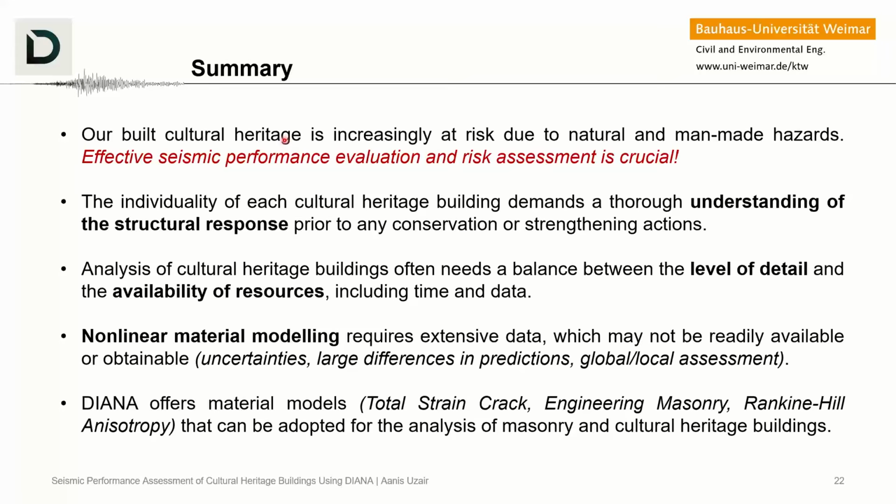Now, Diana in general offers a very good range of material models that can be used or adopted for the analysis of masonry and cultural heritage buildings. For example, the total strain-based crack model for solid elements, or the engineering masonry model if you are using the shell element, and sometimes the Rankine-Hill will also be used, but probably in older models and not really in the newer ones.